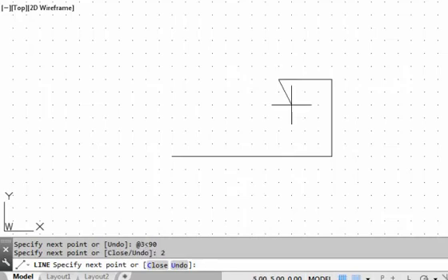For creating simple geometry such as lines, there are 5 different input options to allow us in creating line segments very quickly, depending on the situations. One method might be faster than the other methods, so there is a little bit of decision here. For the next line segment, enter at 0.5 angle -90. This will create a line that is 0.5 units long and moving downward from the previous point. AutoCAD uses the standard engineering notation where counterclockwise is considered positive angle, while a negative angle indicates going clockwise.